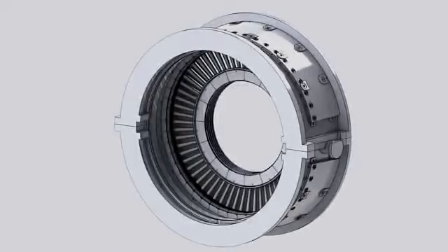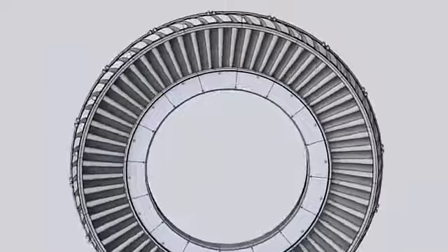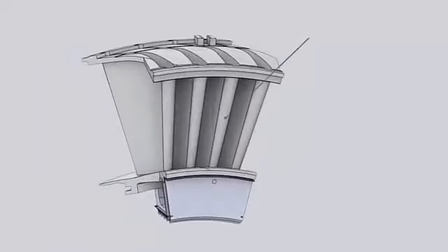The third stage nozzle receives the hot gases from the second stage rotor buckets, expands it further, and directs this flow to the third stage rotor buckets. The third stage nozzle set consists of 16 segments. Each segment contains 4 airfoil partitions.